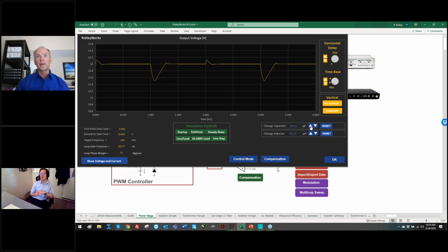So let's clarify that one more time, Ray. When you change the cap value, you're recalculating your control characteristics. So that's everything from what the slope compensation changes for the peak current mode control, and the loop, the type 2 values? Everything that needs to change changes.